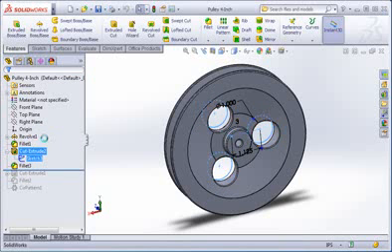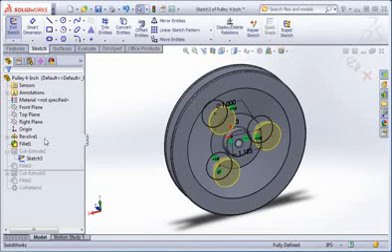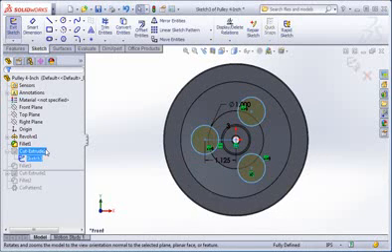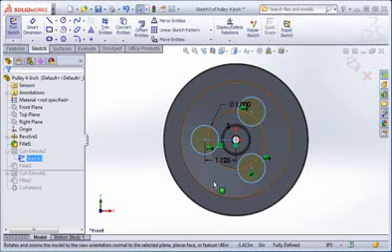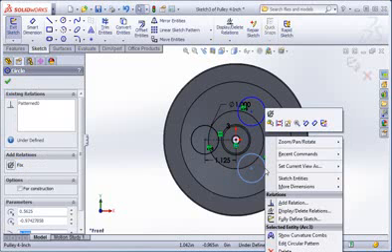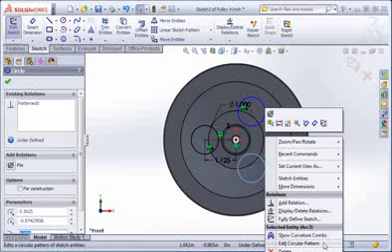Edit Sketch 3, and then set the view to a normal view. Before we can change the number of circles in the pattern, we need to delete the fixed relation. Highlight the relation and then type the delete key. Now right-click on an instance of the pattern and then select Edit Circular Pattern.